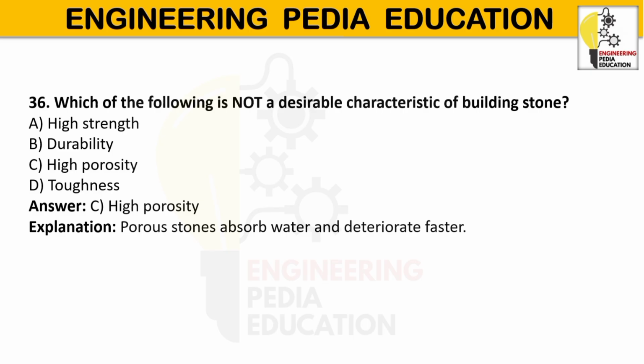High porosity means more voids or pores in the stone. The stone absorbs more water. Water absorption reduces strength and durability. During freezing and thawing, absorbed water can cause cracking. It increases weathering and deterioration.